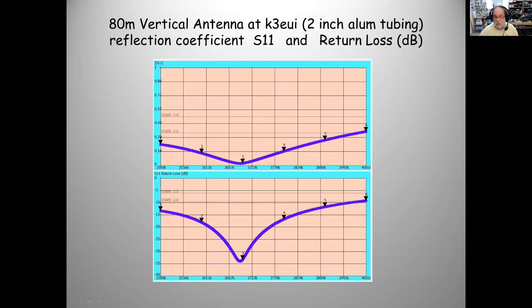So here's the 80 meter band. And look, the reflection is about 29%, about 2% down here. And even at the top of the band, it's only about 30%. In other words, the SWR across the whole antenna is less than 2 to 1. That's nearly impossible to make. Yeah, I made it, and it's fed with about 150 feet of real good quality coax. I can use this anywhere on the 80 meter band.